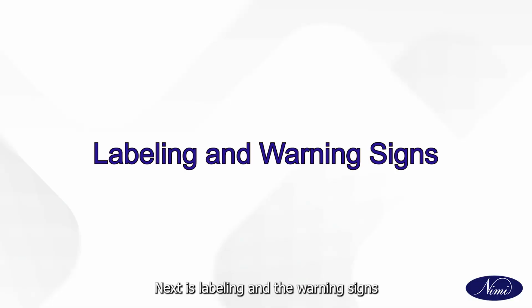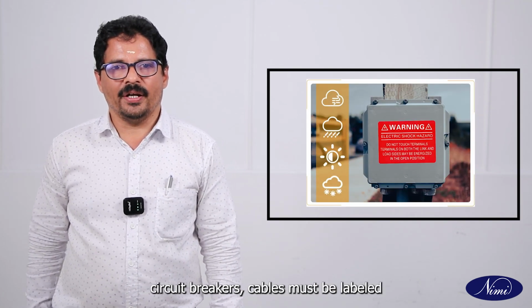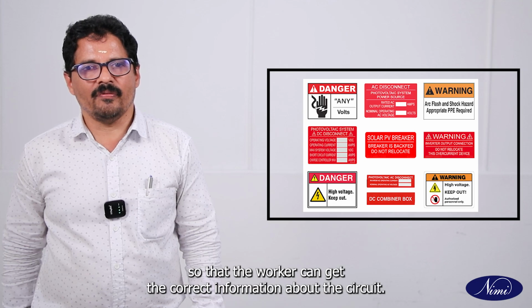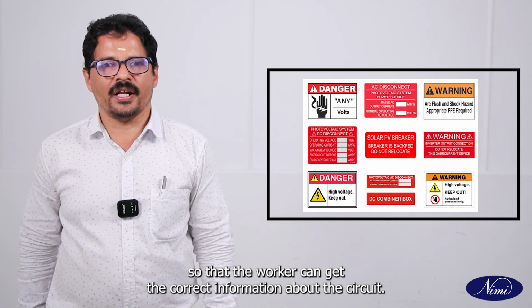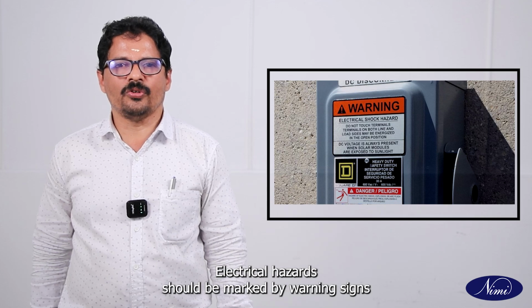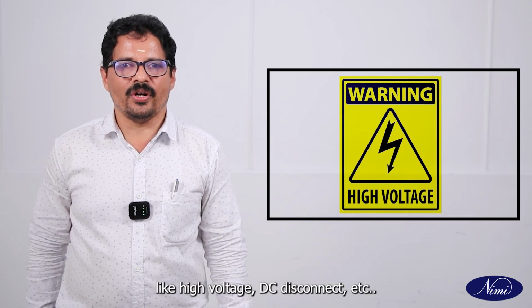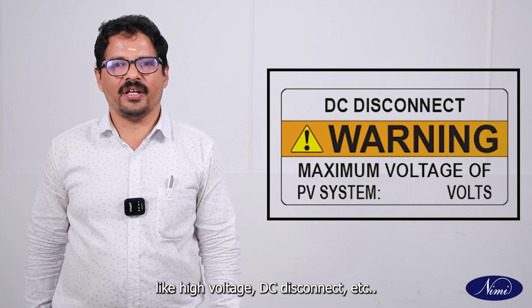Next is labeling and warning signs. All the electrical components like inverters, circuit breakers, cables must be labeled so that the worker can get the correct information about the circuit. Electrical hazards should be marked by warning signs like high voltage, DC disconnect, etc.